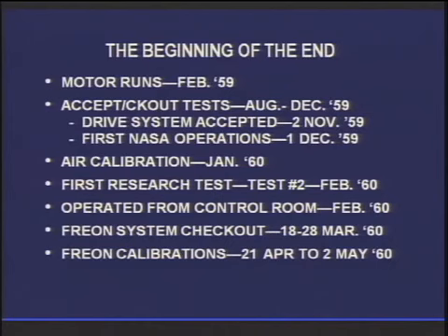The modus operandi in the future would be the electrician would bring the tunnel online at low speed and transfer control to a technician in the control room. The technician in the control room would control the tunnel during the research operations and slow it down, transfer control back to the electrician in the EE room, and take the thing offline.